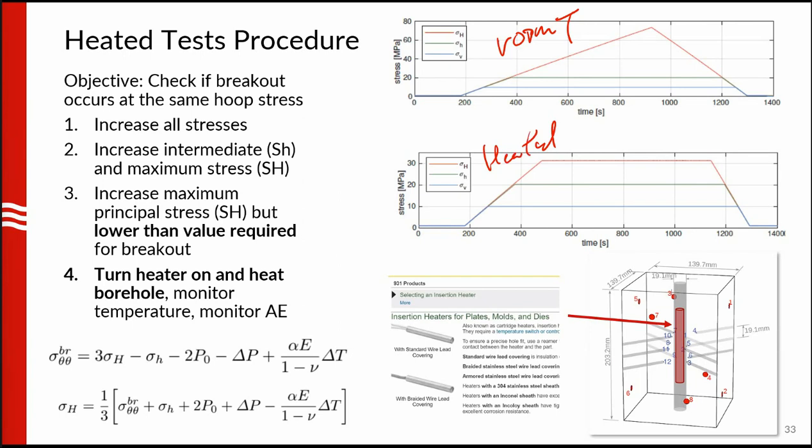And then after we reached that stress state, we had a heater that is inserted into the borehole, and we turned it on to heat the borehole, induce temperature change, and then induce thermal stress, as shown in this last term.